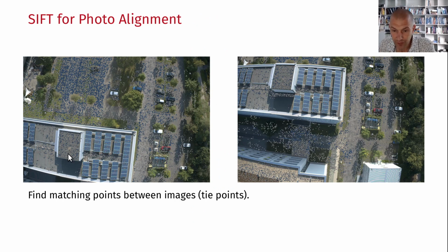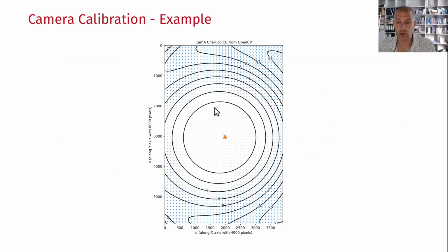If you have the same point that is further towards the corner, for example this car feature here, and the camera is distorted, those pixels would be 40 pixels away, for example. Whereas you're trying to link it to a part of the next picture where you have less distortion at that XY image pixel. So it's really important to have that camera distortion nailed down. Otherwise, your SIFT features cannot be properly linked, or in the end, you have a much noisier point cloud.